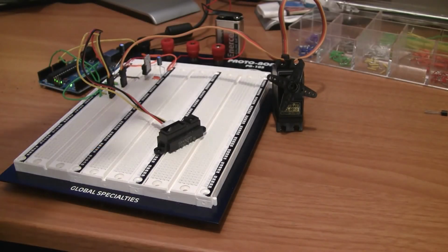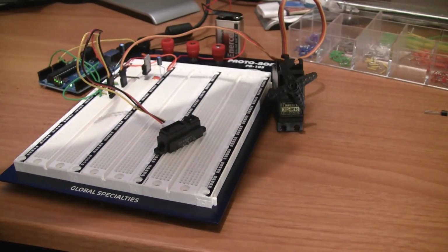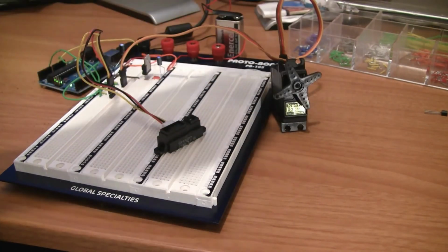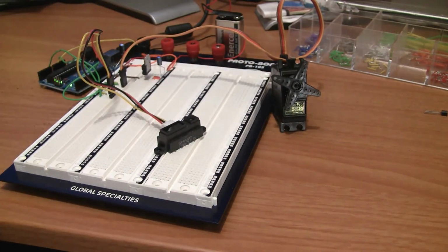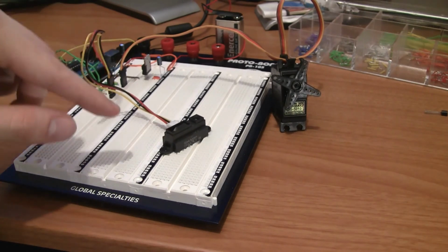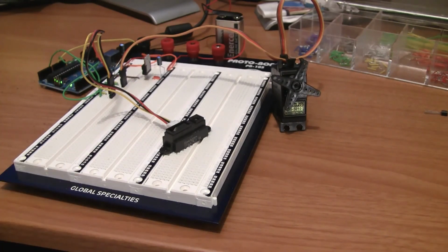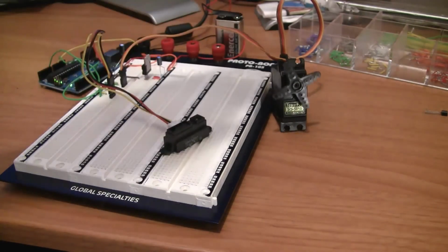Alright, the program's now running. Let's see how it works. Alright, great. You'll notice the servo is a little bit jerky. That's because the values coming from the infrared distance sensor are not perfect. They vary back and forth with each reading. You can fix this either by adding a filter on the input or by doing some math in the program. I'm not going to cover either of those right now, but if you want to look them up, you can. They're pretty straightforward. We'll probably be using some filters to handle analog inputs in future episodes. But for now, this is good enough, and it's pretty cool, huh?